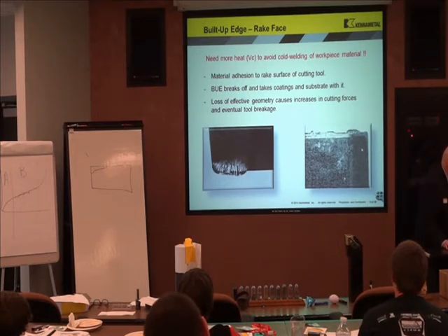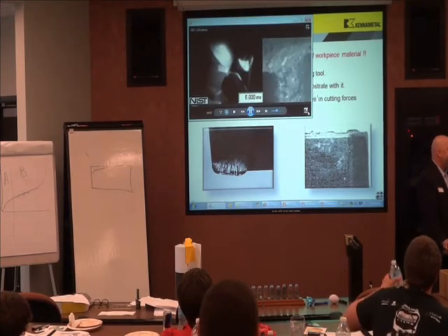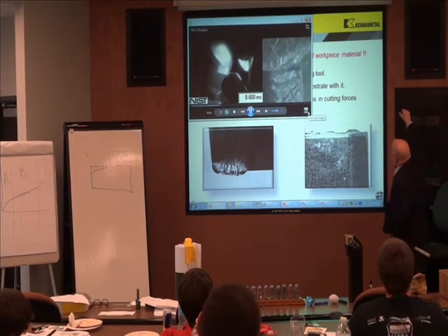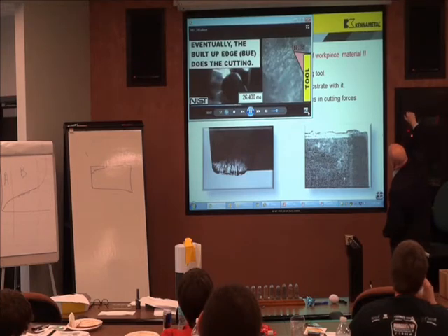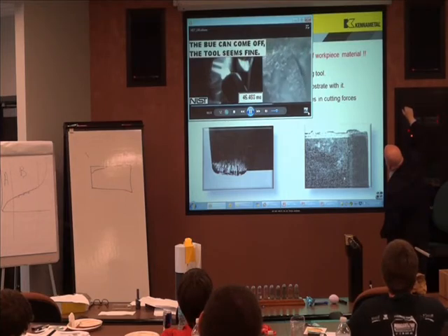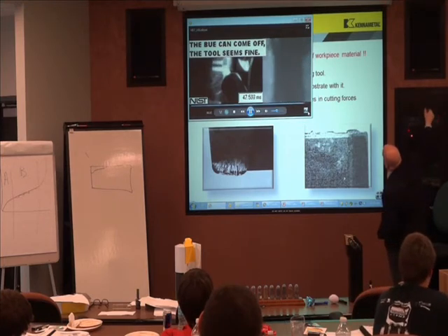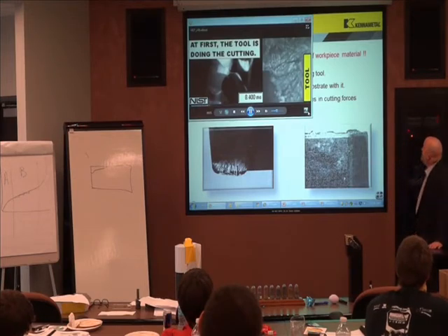This video is kind of hard to see. I'm going to run it a few times. Now what you got going on here, don't pay attention to this side right now. Right here's where the cutting tool is. You see the part that's not moving here? Right here is where my built-up edge is forming. I'm going to run it again. And eventually this built-up edge, this is my cutting tool here. That's the built-up edge, that's the chip. You see the build-up fall off, there's my cutting tool. Now you can see what I'm talking about.